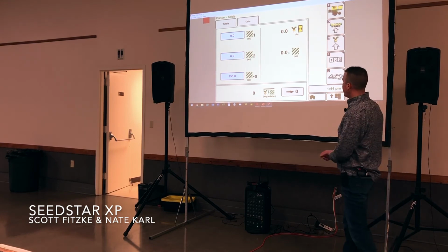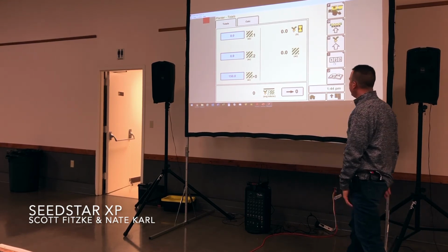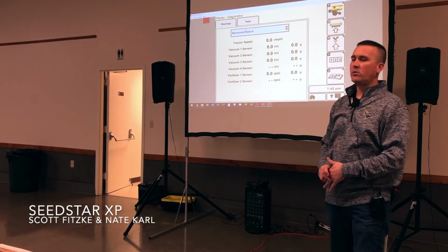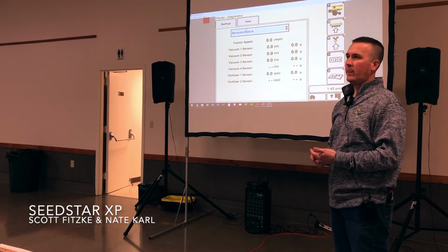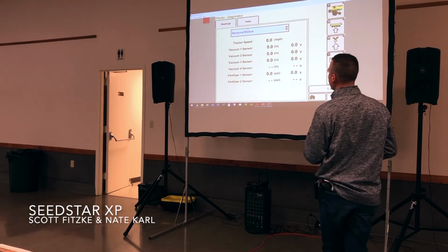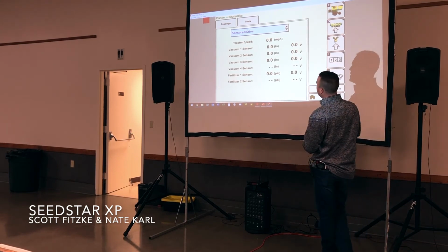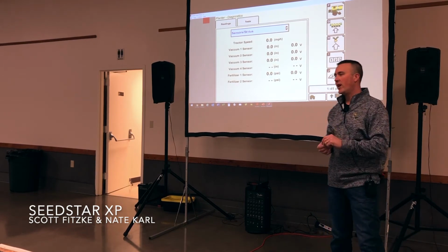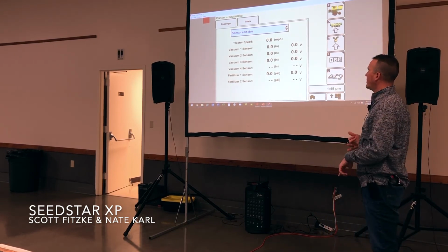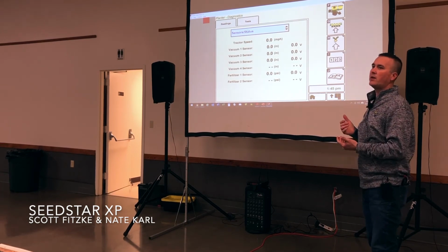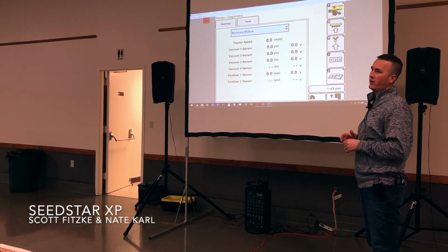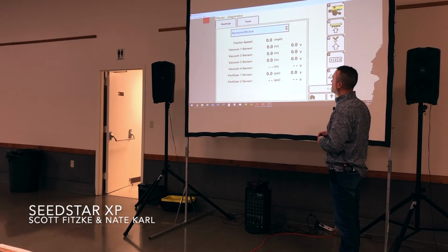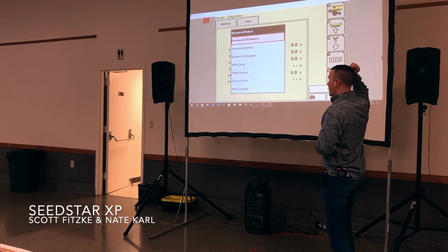All right, the last thing, let's jump in and do diagnostics. This would be one of many tools you could jump into to see if I have an issue with a particular sensor. We can see the expected reading. And more importantly, as we look through the different ones, a lot of them are going to give us a voltage range. So if we've got a pinched wire, or just a sensor that's bad, and I've got good voltage there and that looks okay, that tells me the wiring up to it is probably all right. So you might want to look at just the switch or the sensor itself. We drop that down, there's a few other options in there.